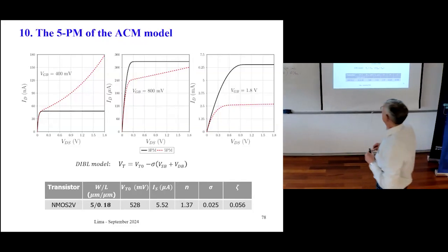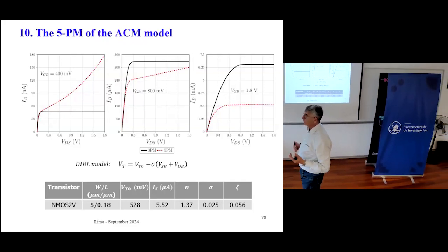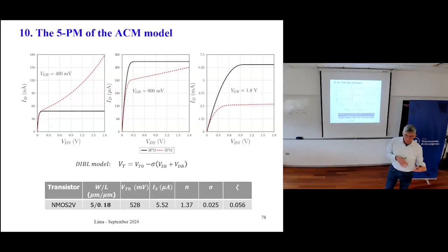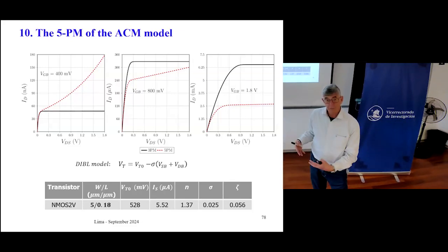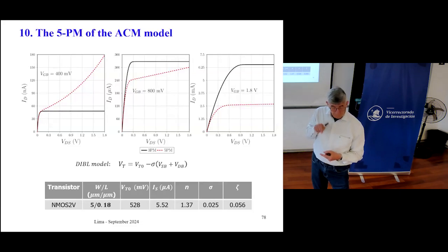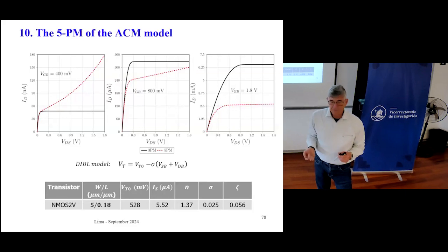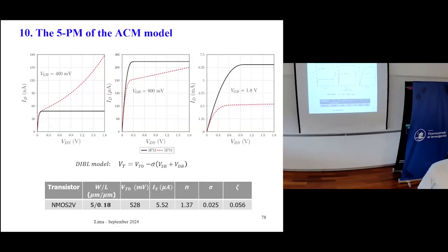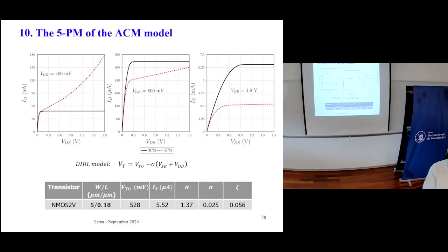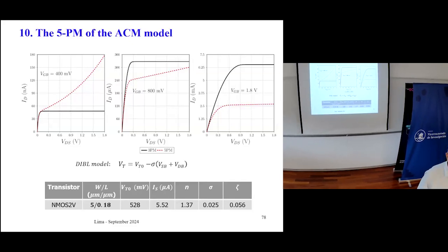You see that the transistor is much more affected by VT in weak inversion than in strong inversion, because in the weak inversion region, subthreshold, the VT affects the drain current exponentially, while in the strong inversion region, the effect is parabolic, and it's subtracted from VG.